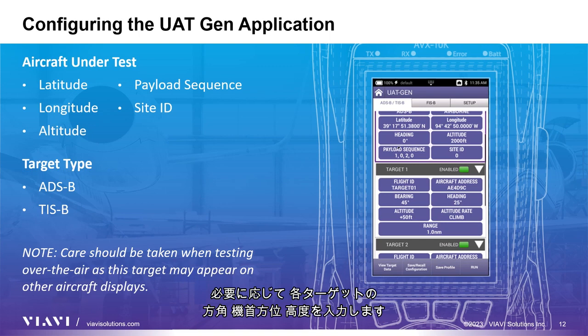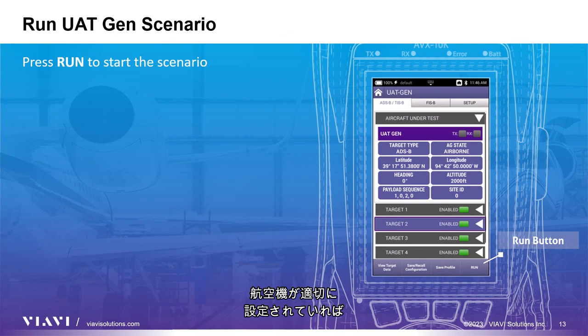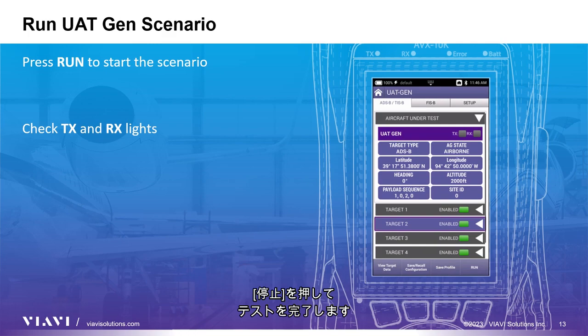Complete each target's bearing, heading, and altitude as required. Once again, please note that care should be taken when testing over the air, as these targets may appear on other aircraft displays. Once everything is set up, press the run key to start the scenario. If the aircraft is configured properly, all targets should be displayed on the aircraft under test. Again, there is not much to see on the AVX itself, other than to verify that the transmit and receive lights are flashing. Once satisfied that the aircraft unit under test is operational, press stop to complete the test.